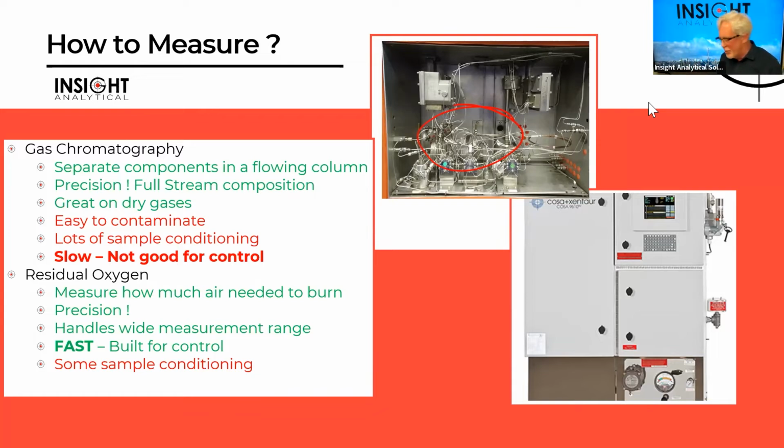So the residual oxygen method is a reliable method for use in some applications. Where people sometimes had trouble with this is when there are a lot of heavy tar-like substances, naphthalenes and things like that, because of how they impact the injection valve. And we're going to start talking about applications like putting these air to fuel ratio analyzers on mobile compressor skids that are being used for fracking wells. We're going to have another set of requirements. They're going to want devices that we can start up quickly, that transport well. And like I said, we're going to look at a couple of other technologies yet.